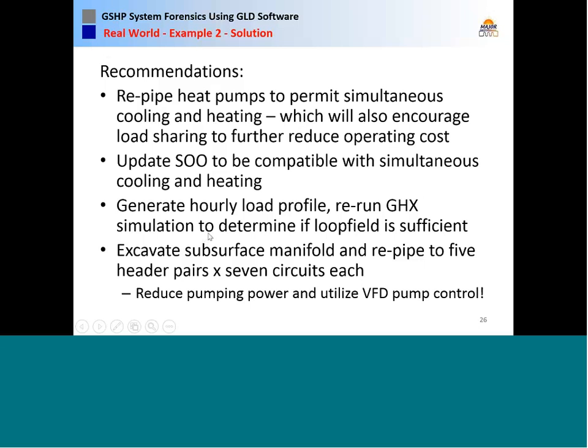Generate an hourly load profile. Rerun the ground loop simulation to determine if we had sufficient ground loop or not, and then reheader the existing loop field and utilize VFD pumping control on the ground loop.